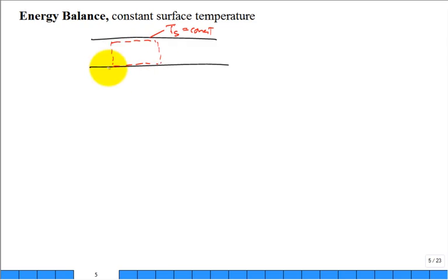That region you can think, if you're thinking of control volume, thermo 1, inlet state 1, outlet state 2, or here at location x plus delta x going down. And it's the same idea. It's what is the rate at which heat is being brought in from the wall into my control volume. That will not be a constant. Remember, it was Q double prime times the perimeter, right? Times delta x.